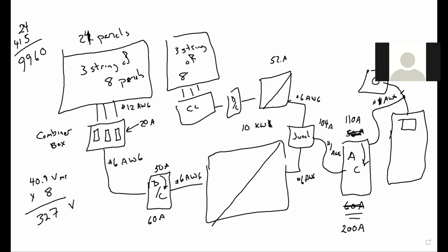That just basically means you're going to have to hire an electrician, come out, cut the wire somewhere between the meter and the main distribution, the circuit breaker box, and put in a bus bar of some sort and connect in there. You can't do it on the other side of the meter because, of course, then you'd be feeding your power out to the grid without getting any credit for it. So this is a pretty complicated system because it's a pretty big system.